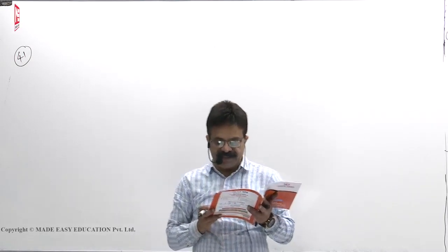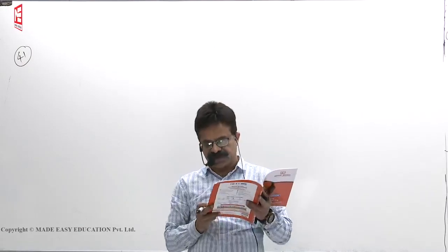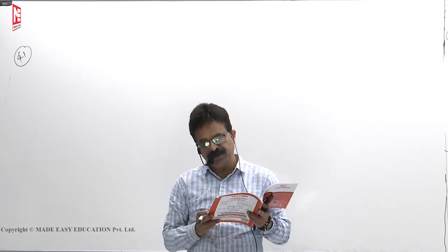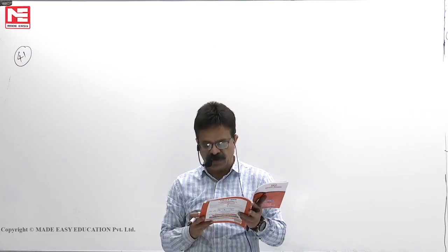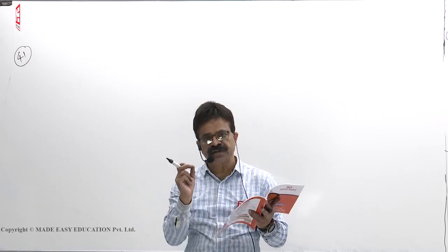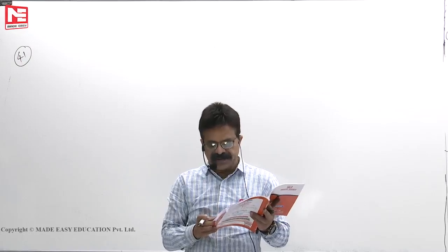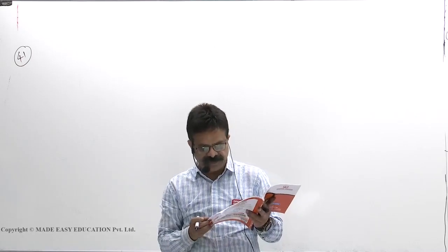Second: stress in a structural member due to several applied loads is the sum of the effects due to each such force applied one at a time, only if Hooke's law holds good. That means loads are applied within the proportionality limit. So 2 is also correct.